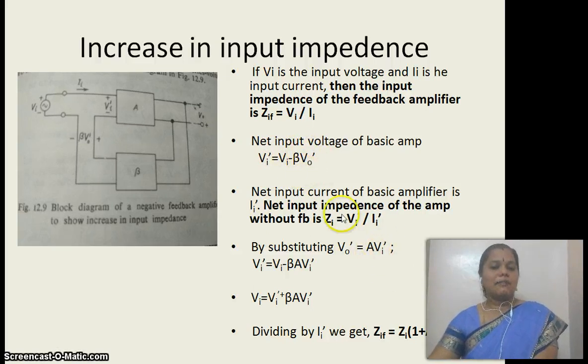So all these things that we have discussed in the calculation of voltage gain expression. So we are just recalling these two expressions, and by substituting them we will end up with input impedance in feedback system increases because the A beta term is in the numerator. When this value is very much greater than 1, obviously your ZIF will always be high.